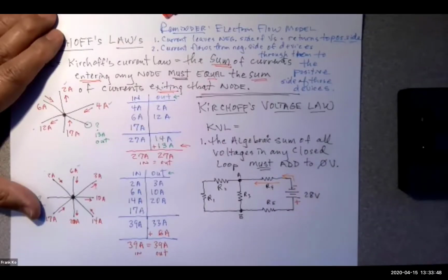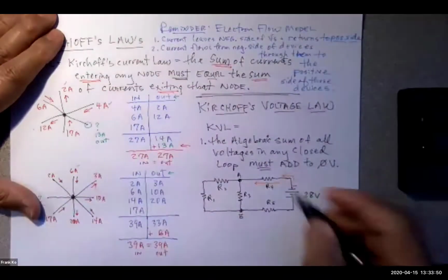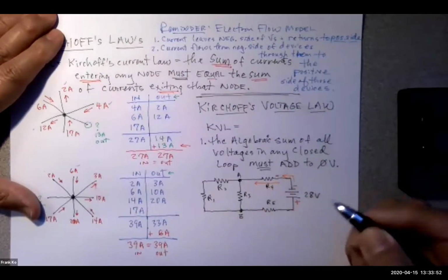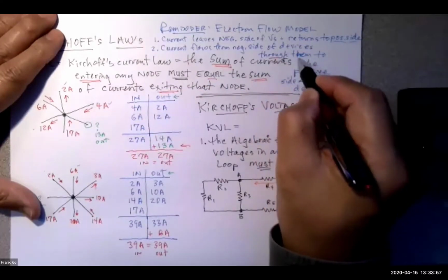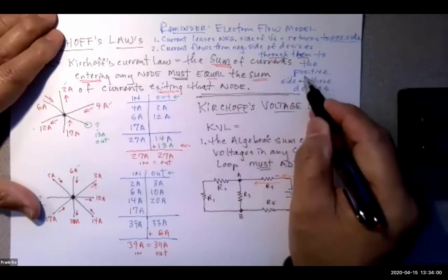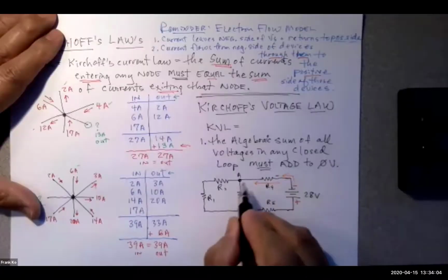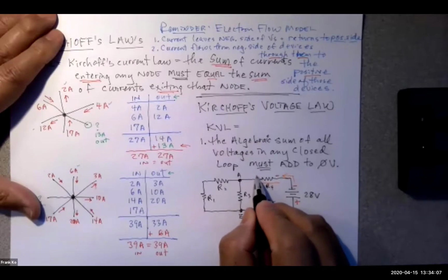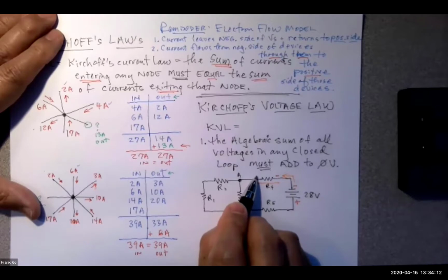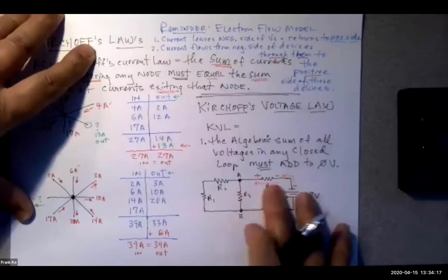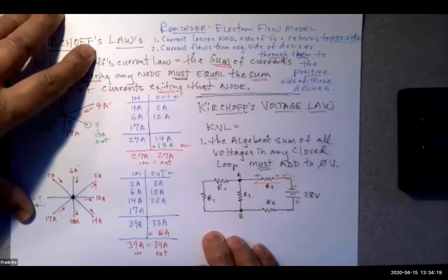So we will have negative over here. This side must be negative because it must flow from the negative side of the device. Then what does it say? Through them, and it ends up where? To the positive side. So that means this side, it flowed through the component. On the left-hand side, this component must be what polarity? This side must be positive. Right there. Are we good with the polarity based on the electron current flow? So far, so good?